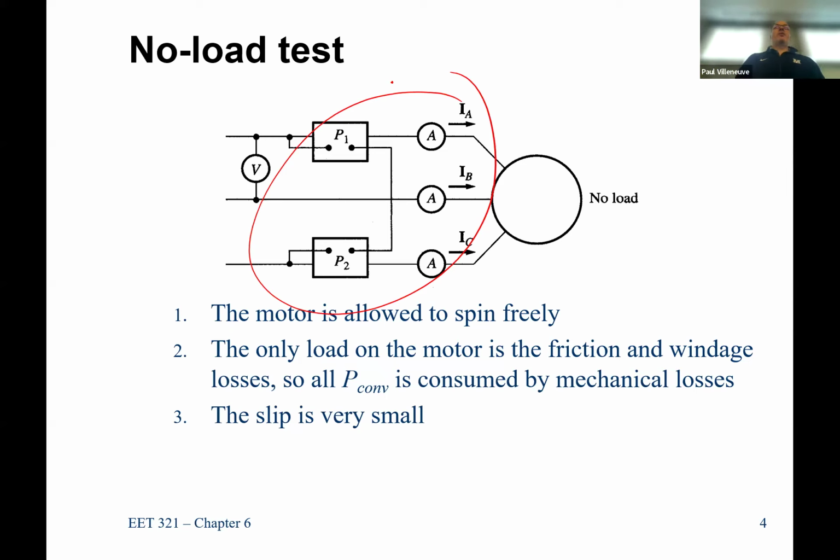So the reason why you do this in the real world is because you want to get an exact measurement. What we did in lab the other day was like, you know what? 1 phase is close enough to get the realistic results. We don't have to be exact, so we'll just use a single phase. But if you want to be more accurate, you can go with 2 watt meter, or you can even get 3 watt meter methods. It just complicates the amount of wiring.